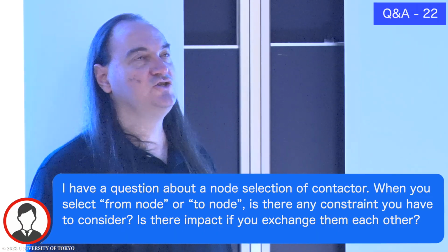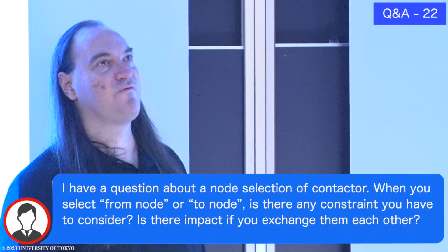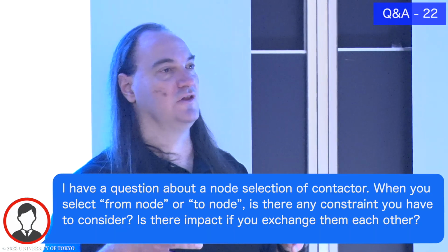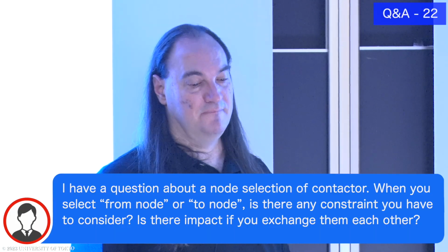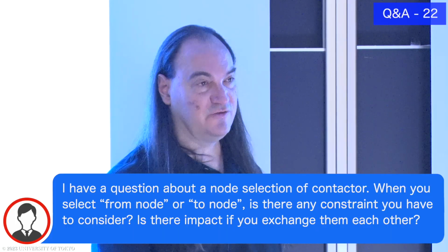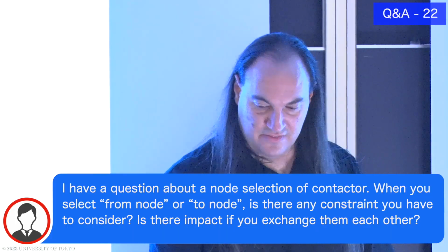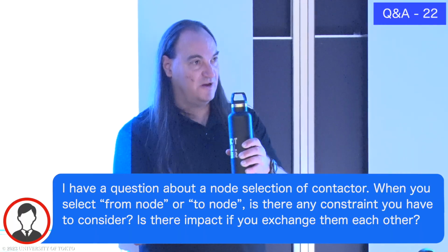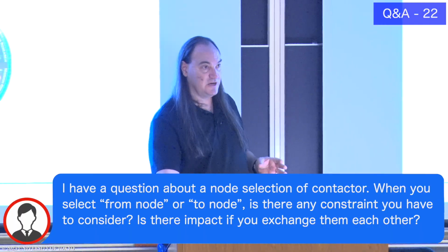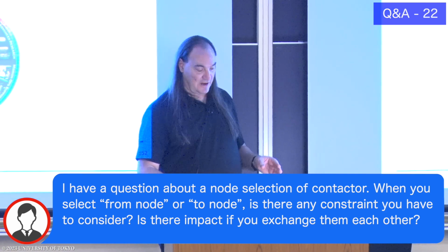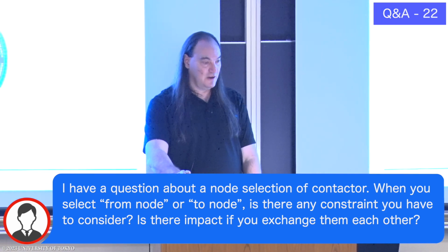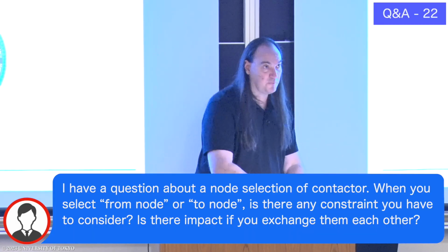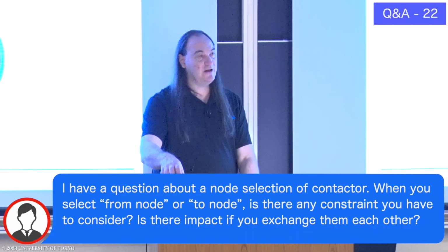Generally, I think you want to go from the smaller surface to the larger surface. If I'm trying to contact this water bottle to this table, I want to divide this into as many small points and deal with the mesh here. If I went the other direction, this table to this water bottle, well, now I have all these other points along here that aren't anywhere near the water bottle.